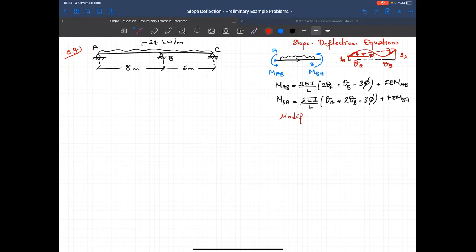And we also derived a version, we call it the modified slope deflection equation, for a specific case. In that case, we said that, okay, that's my member under certain loading. And here I have MAB, but at this end, I know the moment is equal to 0, or this end is free to rotate. In that case, my deformed shape will look like this.